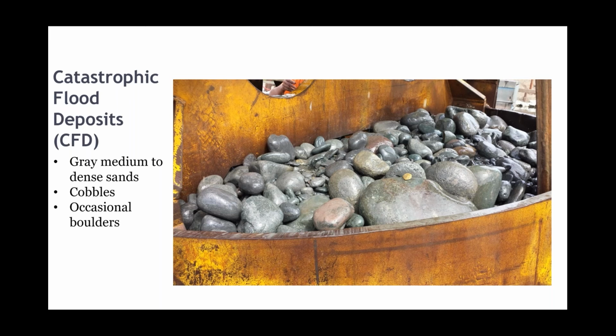SPT would obviously be basically refusal blow counts based on particle size, but may not be a very good indicator of the in situ density. You can imagine how difficult it'd be to push CPT. So really you've got to appreciate how difficult it is to drill and sample and characterize this material. On the other hand, if you imagine a drilled shaft with concrete cast against this material, it doesn't take much imagination to come up with a really decent nominal unit side resistance if we've got good concrete bond to this material. But also you can imagine some difficulties with respect to drilled shaft construction.